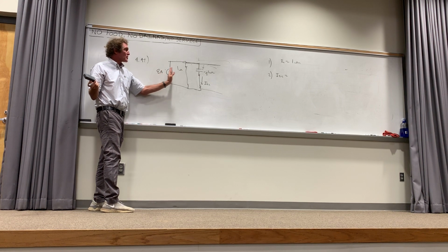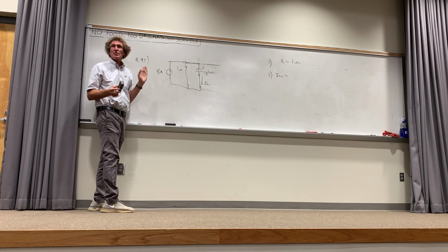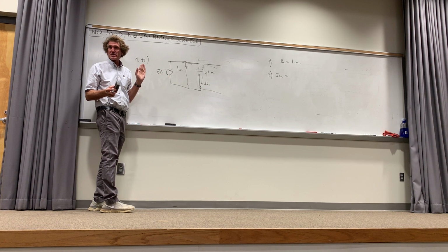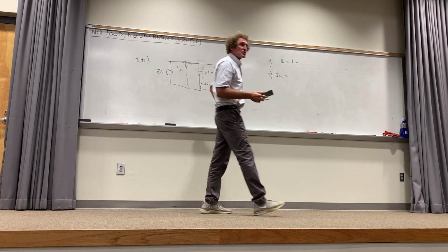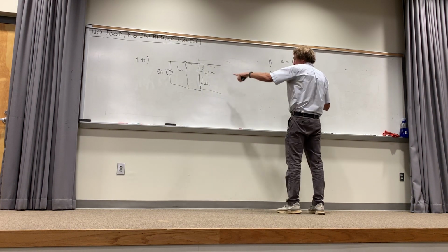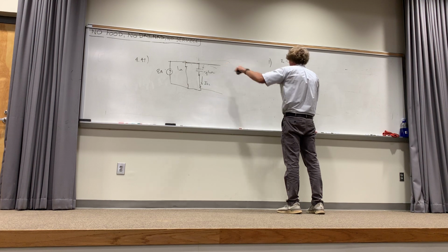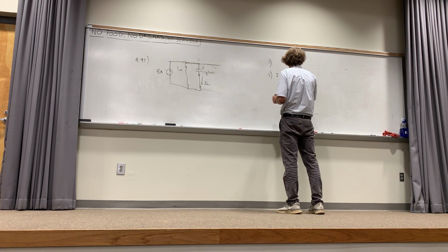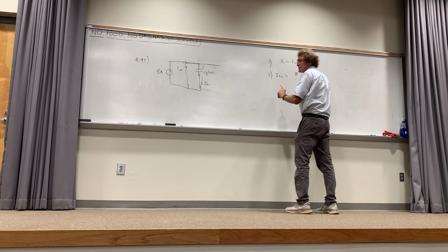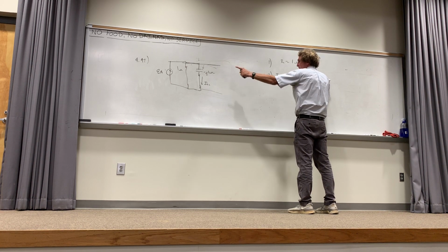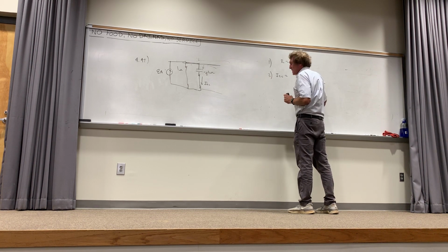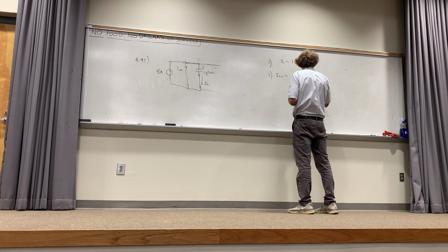Now, these are in parallel, right? So now I'm going to use current division, right? That's a basic thing we studied in the first 2 weeks. So current division says to get that short circuit current, I take the total current, 8 amps, and multiply it by the opposite impedance, 1 ohm, divided by the sum of the two, divided by 1 minus J1.